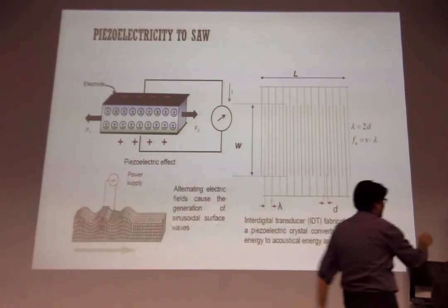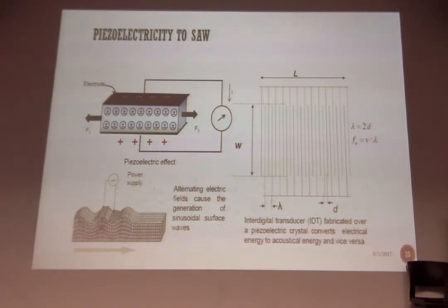So as more and more we push the alternating current here, these mechanical waves will start traveling on the surface. The strain is actually traveling on the surface. The strain is just traveling. It's exactly like what I said about the acoustic waves in the very beginning, that guy who is seeing the pendulum there, the first pendulum was struck, so the last pendulum is moving. How was it moving? Because the second is pushing, the third is pushing, the fourth, and so on. Same thing here. These IDTs, when I apply electric potential, there is a deformation. Actually, these are particle movements. These particle movements will push the adjacent particle, the next will push the other one, and so on, and there will be waves on the surface.